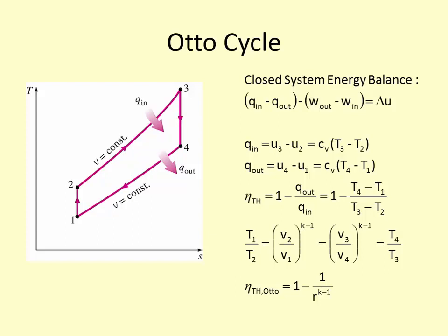And then if we want to calculate the thermal efficiency of this system, it's not 1 minus TH over TL, because that would be the thermal efficiency of a Carnot cycle. We could use that to find a maximum, but we have to actually use this Q out and the Q in. But because we're using C sub V and a change in temperature, we can use these delta T's in order to analyze our thermal efficiency. Because of some other assumptions, the cold air standard assumption that it's an ideal gas, part of it is isentropic, then we can also say that from state 1 to state 2, the volume ratio is going to be equal to this, and the state 3 to state 4, similar processes followed.